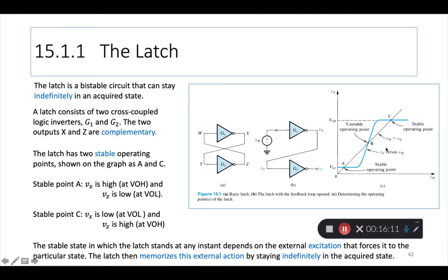Now what is this graph? It is some kind of transfer function, right? An input to output relationship. So when one of these inputs, for example VW, is low, closer to 0, the output is also close to 0. Similarly, when this input VW goes higher, we see that the output also has gone higher. So if you think of VW as the input and this VZ as the output, then they kind of work in synchronization.